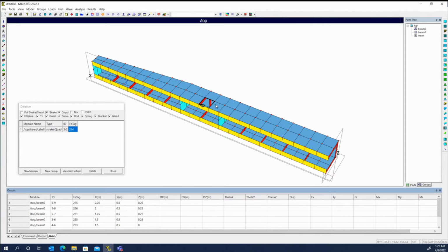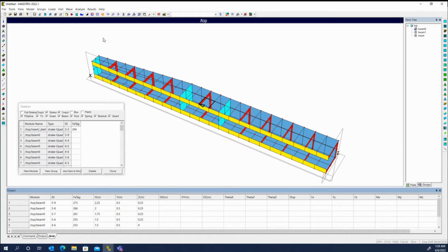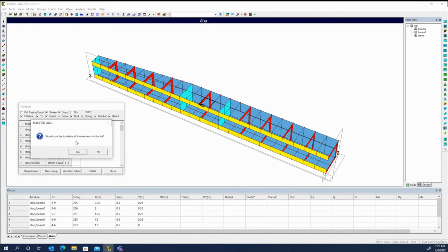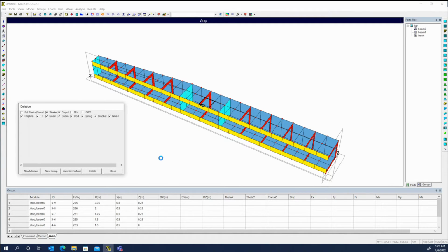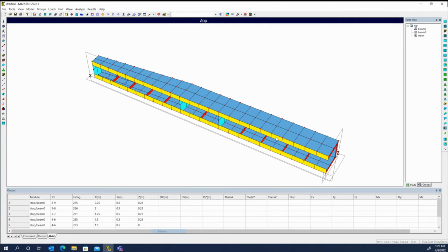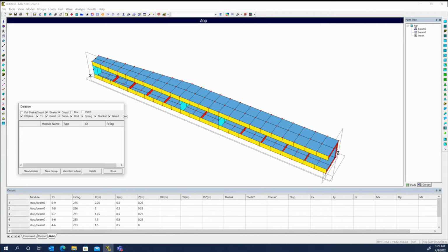If I just grab this one quad, and if I say add by seed, it's going to find all the planar similar quads within a certain angular tolerance, and I think it's about a 20-degree difference. I think what shows up is 160. I'm going to close this and not delete the elements and hit refresh so they come back.